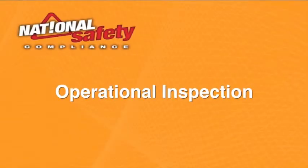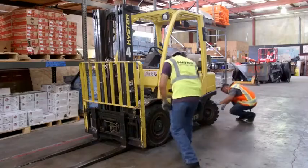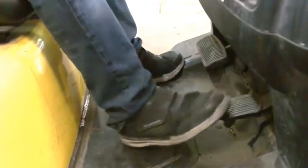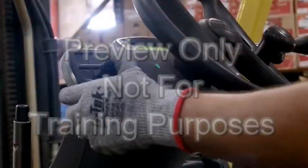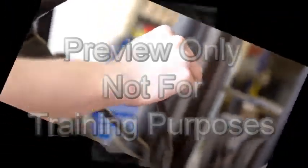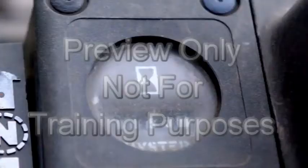Operational inspection. After completing the pre-operational inspection, operators should conduct an operational inspection with the engine running. This inspection includes accelerator linkage, inch control if equipped, brakes, steering, drive control, front and back, tilt control, forward and back, hoist and lowering control, attachment control, horn, backup alarm, hour meter.